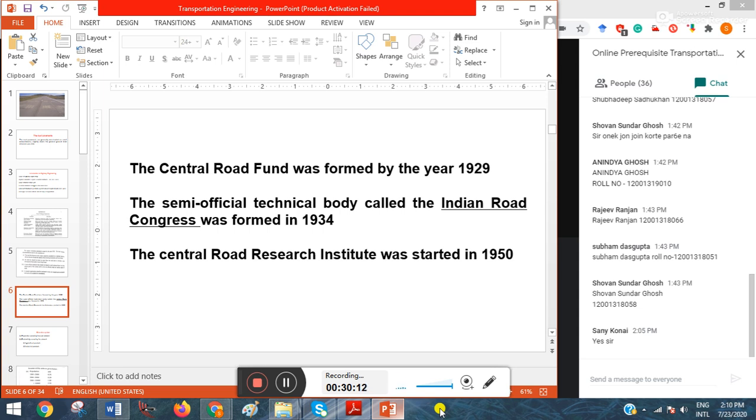In this first 20-year road development plan, popularly known as the Nagpur Road Plan, all roads were classified into 5 categories, and a 20-year development program for the period 1943 to 63 was finalized. At the end of this plan, the target road length aimed at was 16 km per 100 square kilometer area of the country.